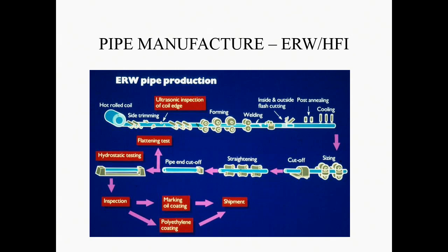After the welding stage, there's often a trimming of the excess flash. So if you push two materials together and then heat them up so they melt, and you squeeze it, some of that molten metal will come out up and below. Because we're squeezing it to maintain the shape, we tend to get the weld metal sticking up and sticking down into the pipe much more, and we have to trim those off with a simple cutting tool. Otherwise, if a pig was going down this pipe, it would stop when it got to the weld.